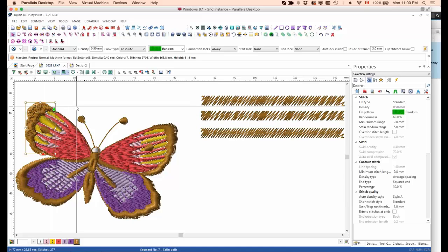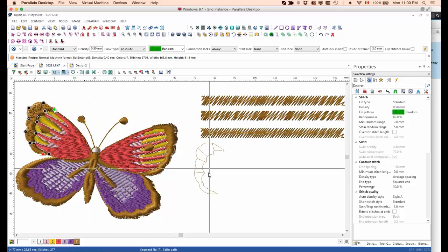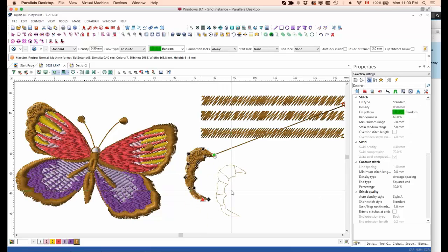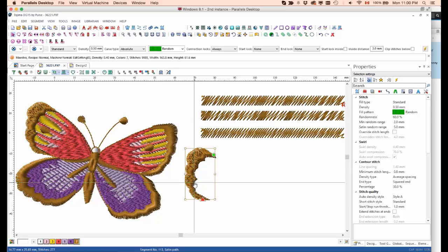If you wanted to make the right side the same as the left side, can you copy the properties, or do you have to set them again manually? No, well, the properties can be copied and pasted with these two symbols here. But the duplicate button is very different. For example, if I select this segment here and I press Control D, you see I'm duplicating this segment. So now I have an identical copy basically. But if I want to have this one, let's say, to be matching this part here, then I need to work on it. I need to reflect it.